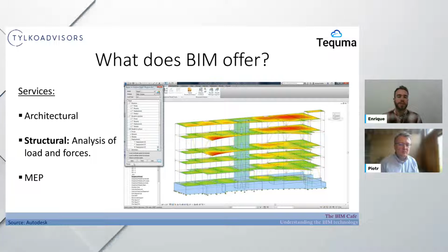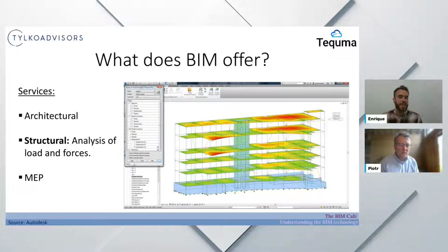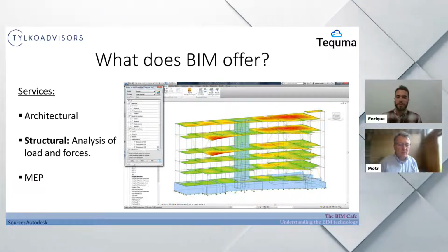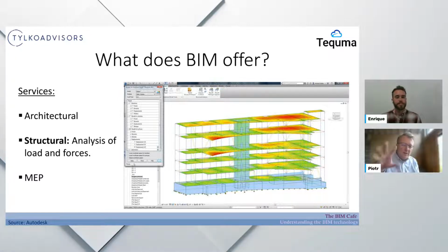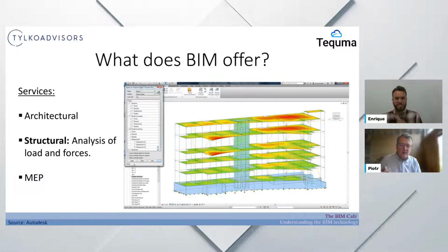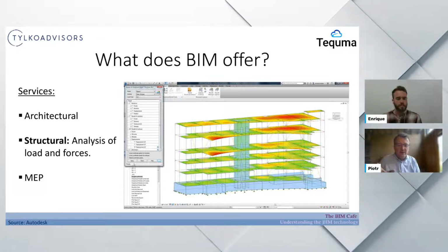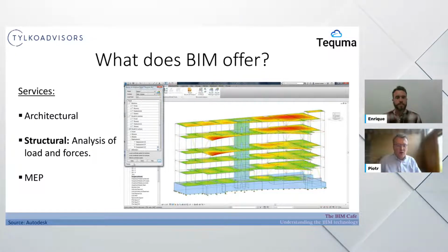This is important because we cannot run the simulation of the forces if we don't know the weight, for example, the density of those materials. So if the providers give the density of materials in these BIM files, we can do those simulations and use that data, which is not a link now, but will be linked to the whole project. So, for example, at this moment, I can change the manufacturer because that's a different characteristic. I can go for another manufacturer which allows me to keep the building safe, and it will keep the characteristics that are desired, right?